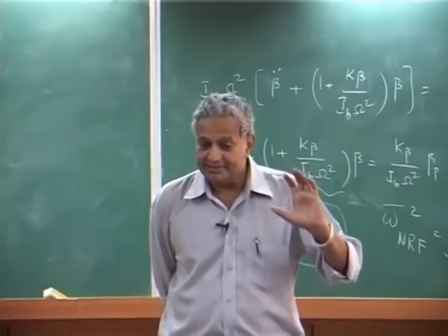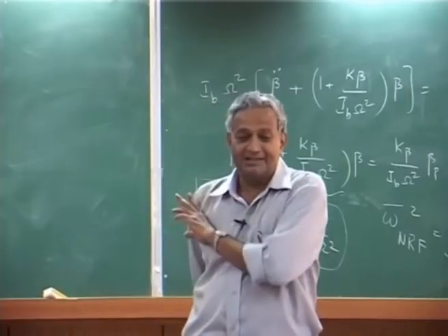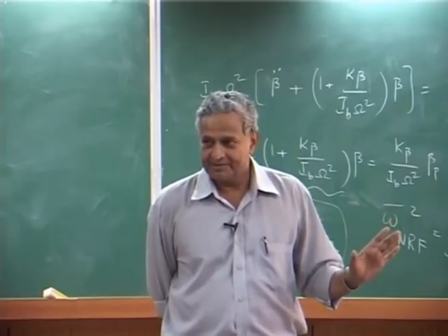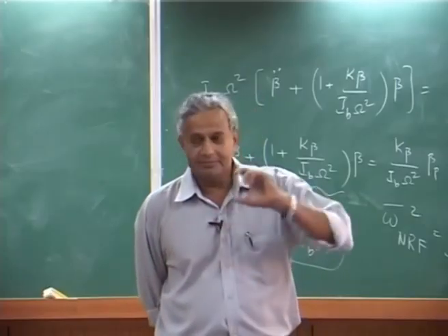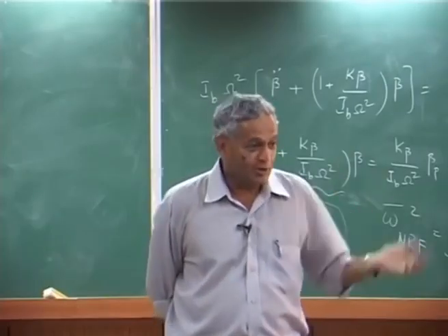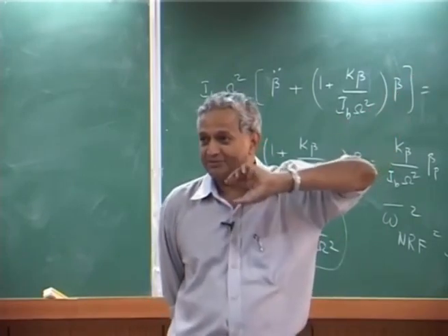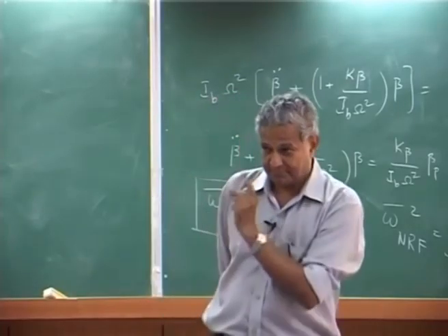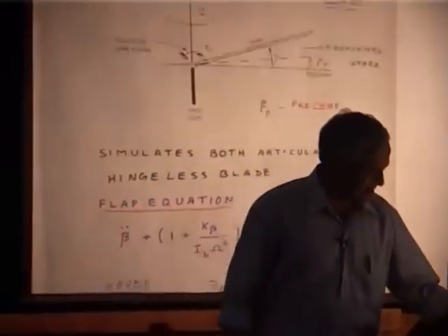Actually, you will find the industry in selecting the rotor system, rotor blade, this is where the major effort goes on. What should be my flap frequency? Okay. It is a real challenging, because this is going to affect my performance, control characteristics, okay, my loads, hub movement, many quantities. Okay. That is why the flap frequency is a very dominant frequency. That is the first flap natural frequency, first natural frequency. We will come to that influence part later.